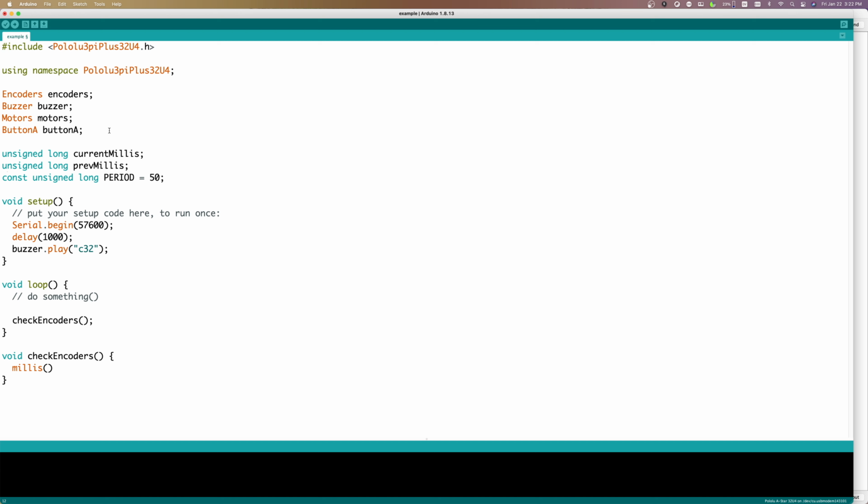One of the most interesting parts of programming in robotics is that you're dealing with the physical world. And let's say I make this 500, right? So every half second I check the encoders. The problem with that is that if I want to go 12 inches, I could very well overshoot my 12 inches by a pretty significant margin, because I'm not checking the encoders often enough to know that I actually went the 12 inches.